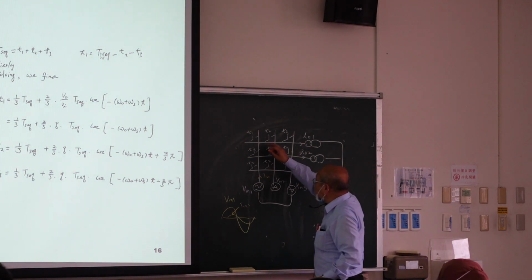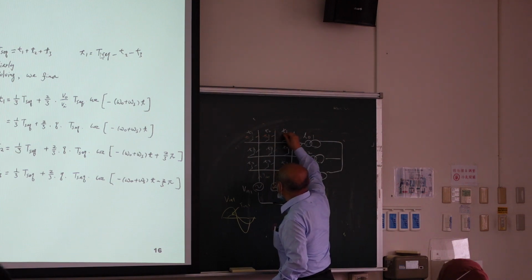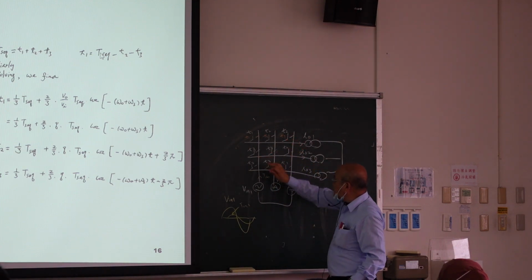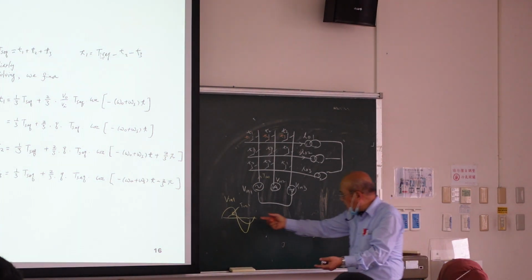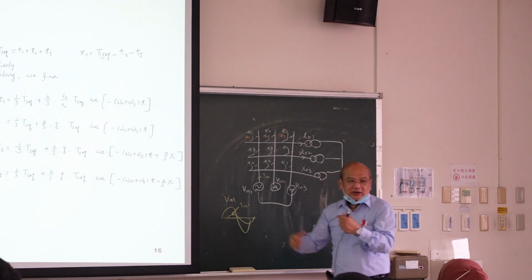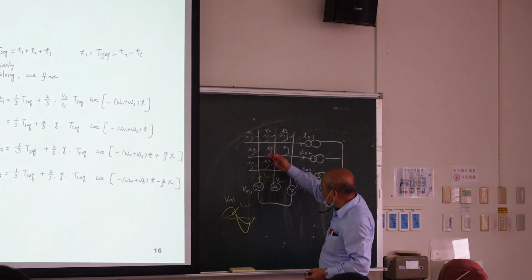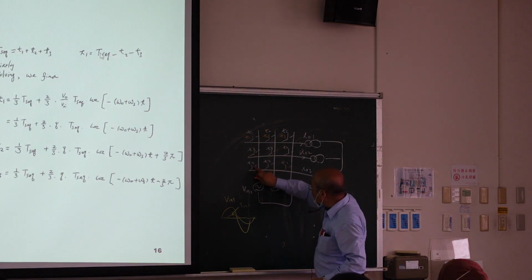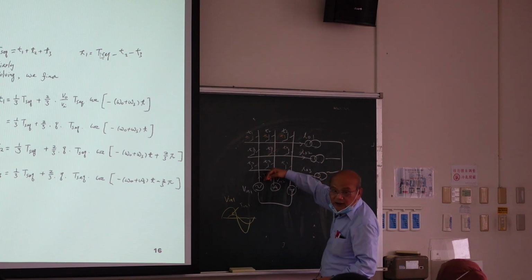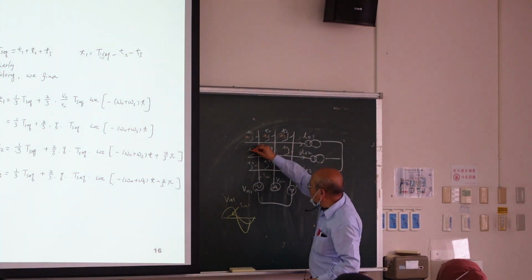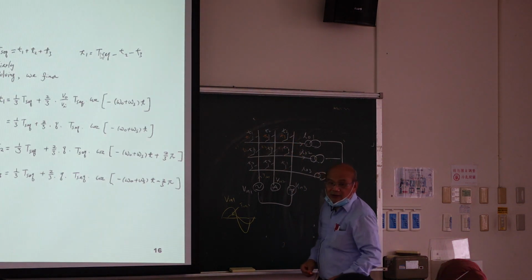Then I think T1, T2, T3, like T1, T2, T3. But here, I want to reverse, right? Change the current to become heating. So I need to reverse. How can I reverse? So I switch these two. So this becomes back. Original T3, T1, T2. I change this to here. I change this to here. So this is T2, T3, T1, right?